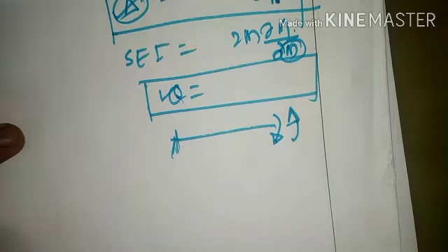In case it is not present, then we need to introduce a dummy, virtual or fictitious moment at that particular position. Then only we partially differentiate it. If we don't have a moment and then differentiate, obviously the whole term will come out as 0. As a result, the slope at any section throughout the length of the beam will remain 0, which is practically not possible.